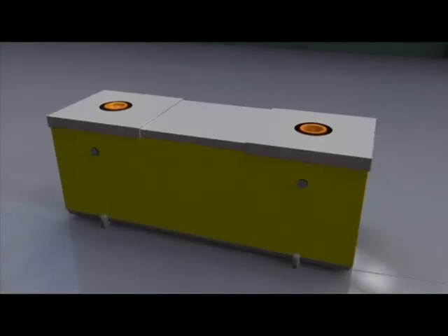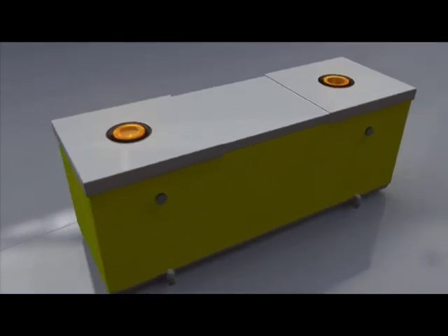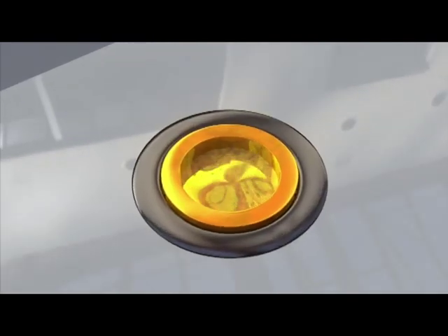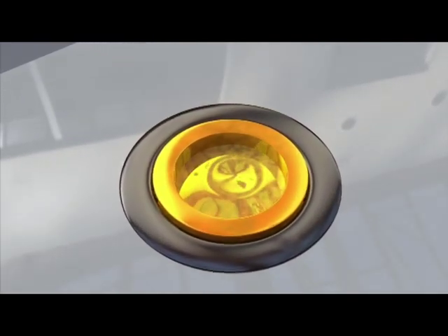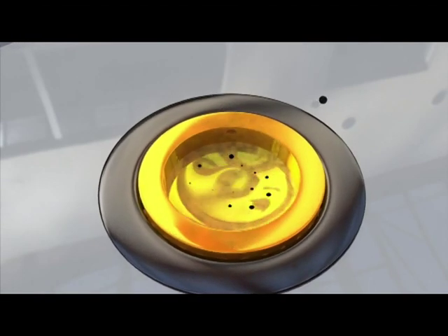The use of aluminum casting material and processes to produce a copper rotor would fracture the die surface in a short period of time. Apart from that, the oxidization of pure copper liquids needs to be prevented, as the cuprous oxide particulates formed in the process of oxidization would exert a dramatic negative influence on copper conductivity.